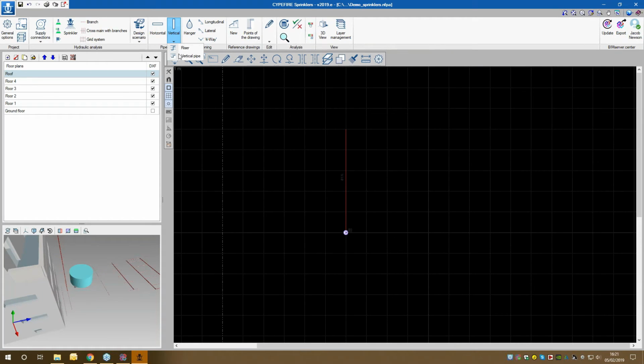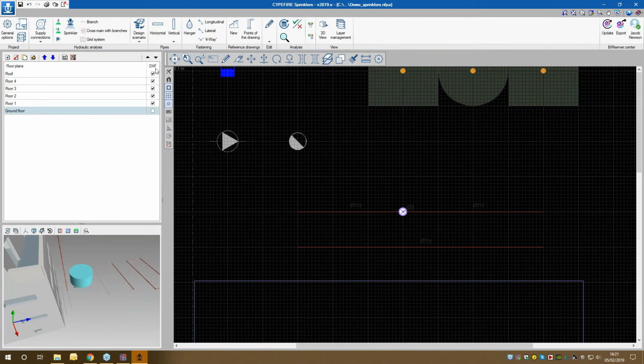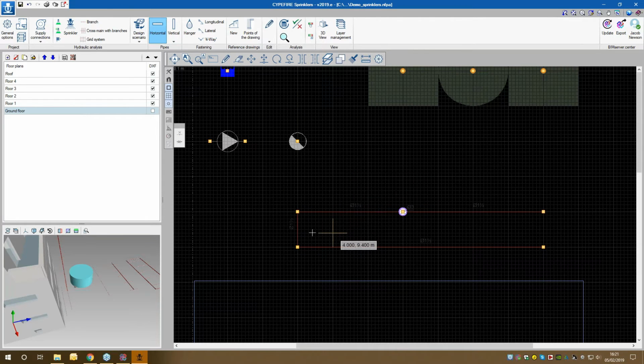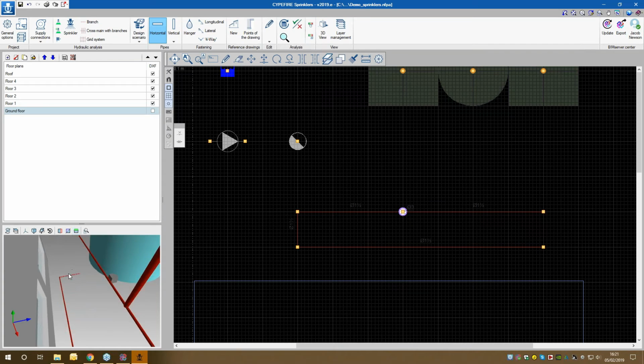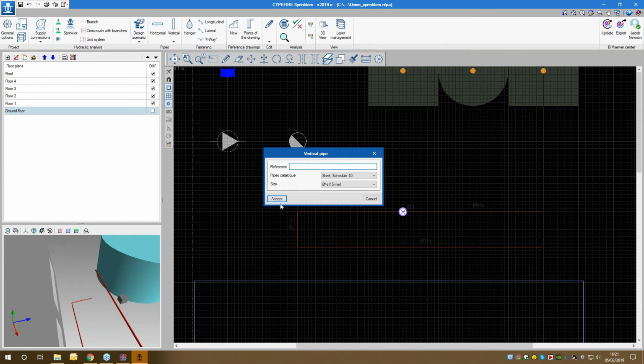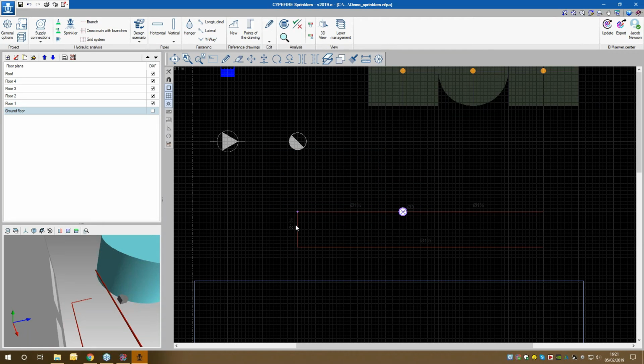And the other is known as a vertical pipe. So I go back down, and if I connect my horizontal pipes, in the diagram at least, we can see that obviously they're at different heights, so there is no connection. And this is where you use the riser pipe to connect pipes that are on the same level, same floor, but at different heights. So if I attach that there at the connection, and I refresh, they're connected with a riser.